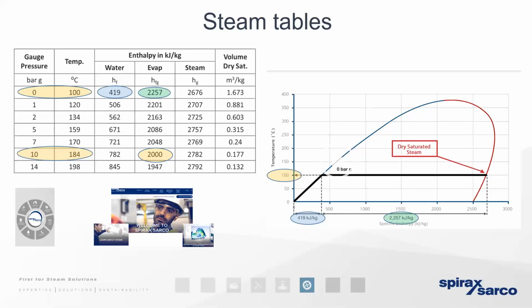But those two heat value properties combined mean that steam at a higher pressure has got more total heat energy contained within it. So we went through the reasons why 2 weeks ago we generate steam at a high pressure. Higher pressure steam means that there's more motive energy in it for distribution to the processes.